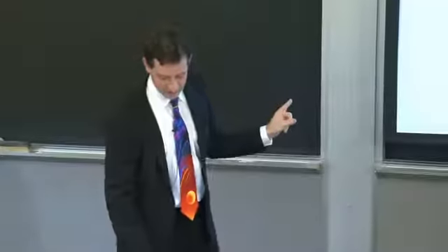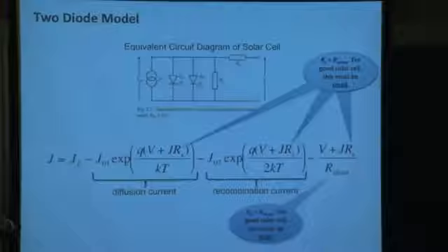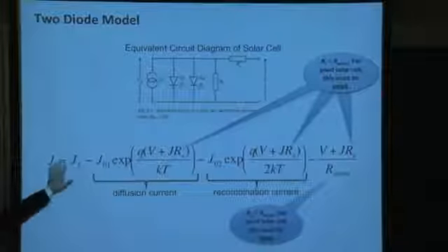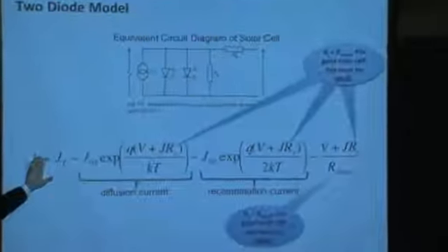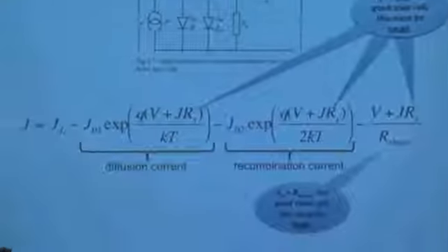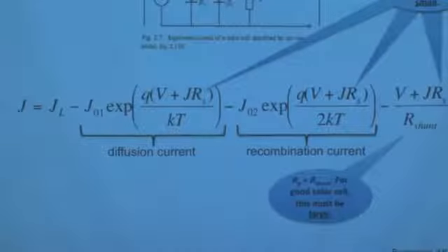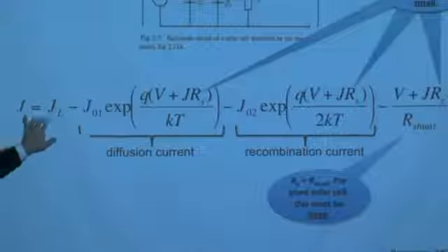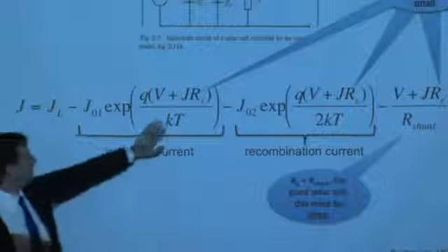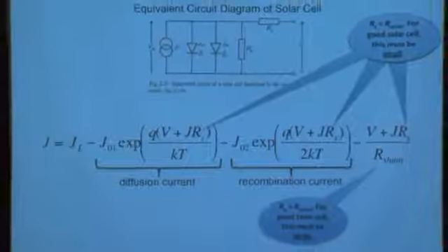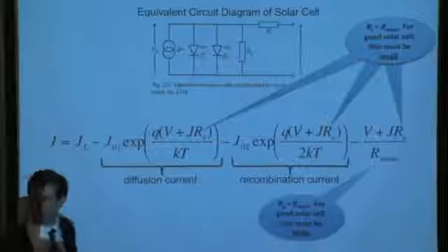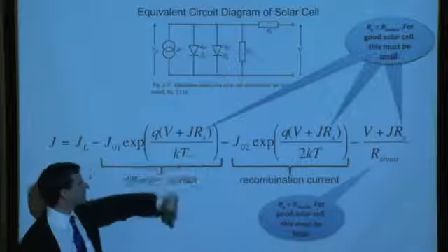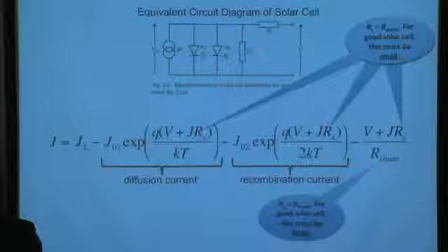So the idea now is to begin probing that junction condition. We talked about the ideal diode equation, and now we're going to piece through it once again. This is your current density here, and I believe if you really want to be precise about this, you should use straight current and not current density. Reason being, if you look at current resistance product, that gives you voltage. But current density resistance product gives you essentially a voltage density, which is not a unit that we typically use. So just keep that in mind as a small little asterisk.